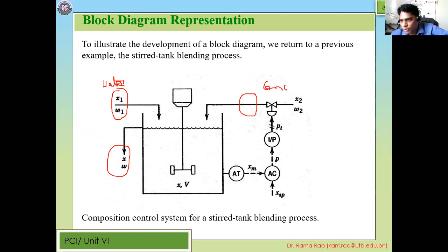So depending upon what you want, you can pump the required amount of constant solution so that we get a desired solution. Okay. Because we are not monitoring the output, we want to monitor the input. If you want to know how much concentration we are getting, we should have an instrument which can measure the concentration. So here X is the concentration. We are assuming that this whole tank is perfectly mixed and there are no heat losses, so the concentration is uniform.